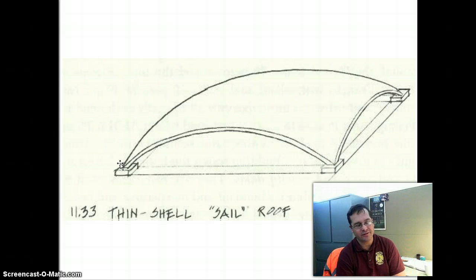So similar process here. The upshot is that the formwork is basically just the balloon. The balloon is inflated, the concrete is sprayed on the exterior of it, it's given sufficient time to harden, and then the balloon is deflated. The balloon gets packed up and taken to the next job site. So there's really very little overhead cost in this operation. Once the balloon's constructed, they can make these things rapidly and for not very much money.